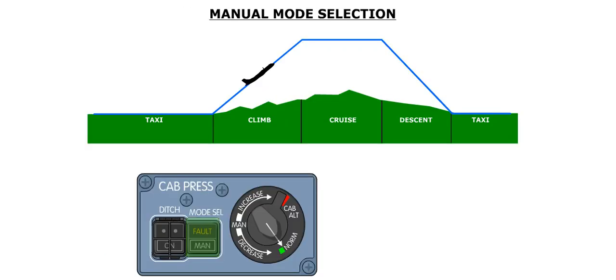The pressurization system can be placed in the manual mode of operation by placing the mode selection push button to the released out position. This will disable the digital controller, and the electro-pneumatic outflow valve will close. The white manual caption will illuminate, and an amber air automatic pressurization message is displayed on the EWD. Click on the mode selection push button to continue.